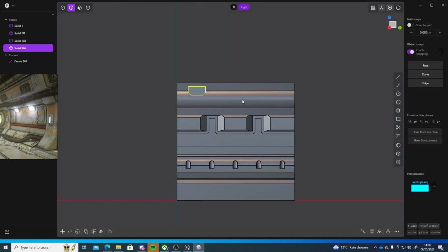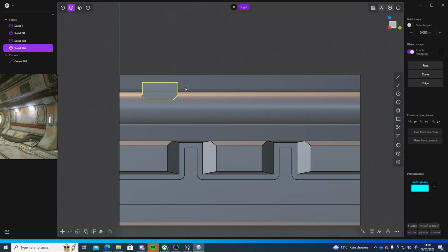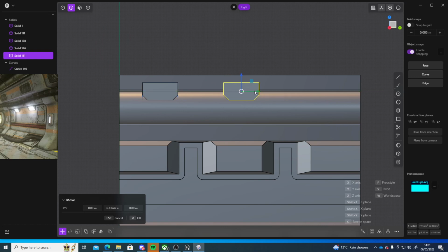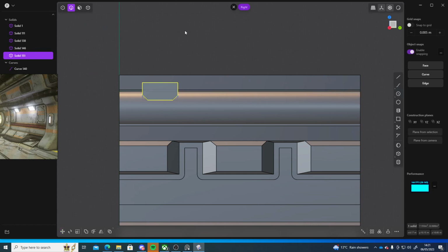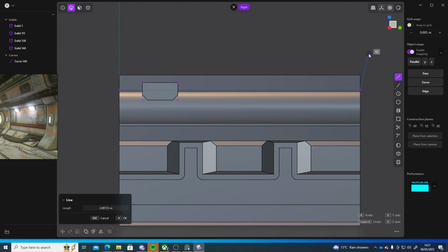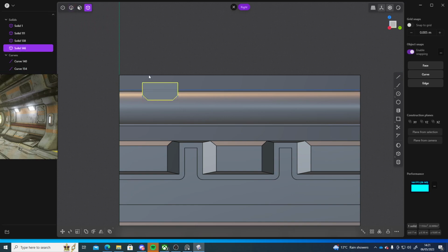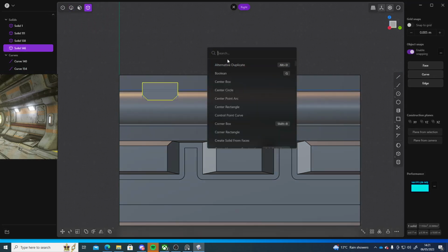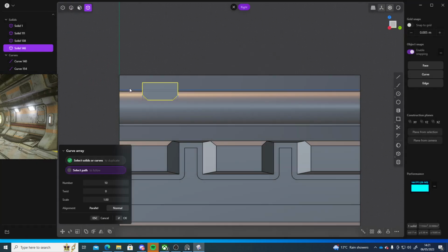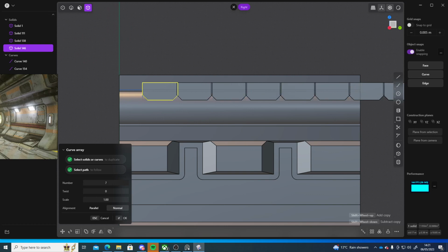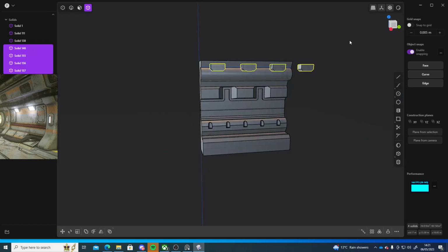Then I can go back into front view and just do Shift D, move it over, Shift D, move it over. I'm gonna do the linear array, I think, just because I think we can get uniform size. So from here to here, right click, select this, press F, array, curve array, select that curve, drop this down. So the spacing between here and here and that little bit will be about right, I think.